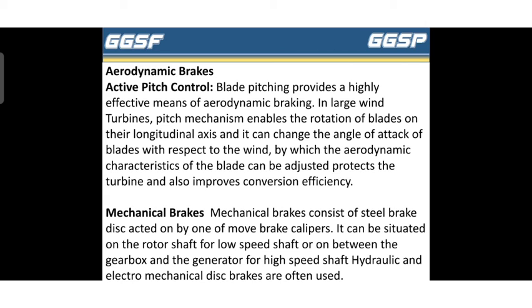In a large wind turbine, the pitch mechanism enables rotation about the longitudinal axis and can change the angle of attack of the blades with respect to the wind, by which the aerodynamic characteristics of the blades can be adjusted to protect the turbine and also improve conversion efficiency.